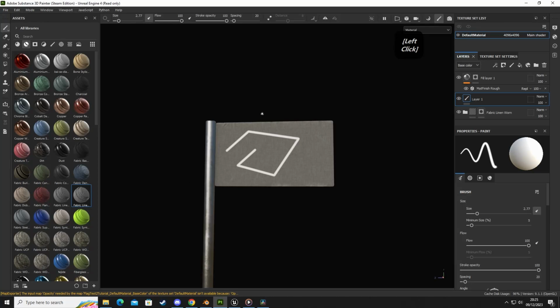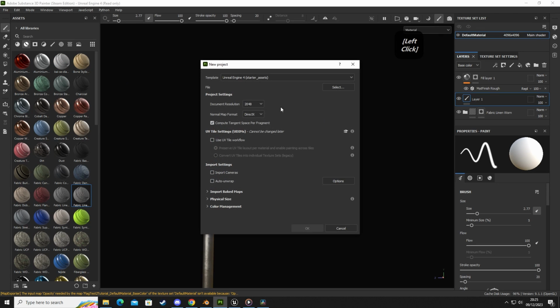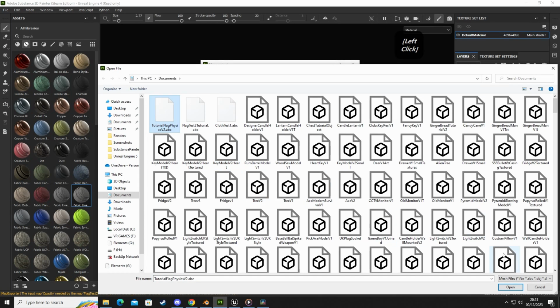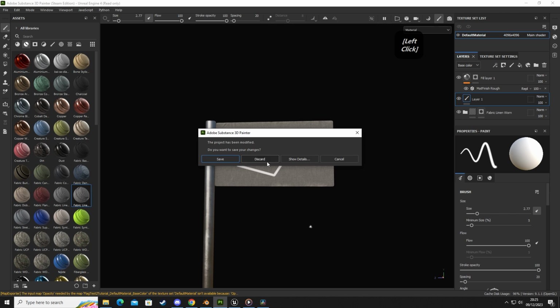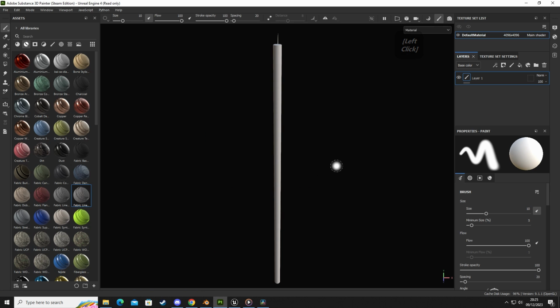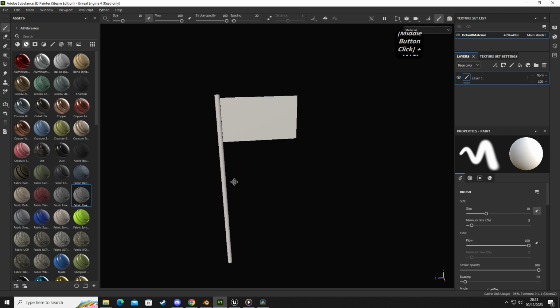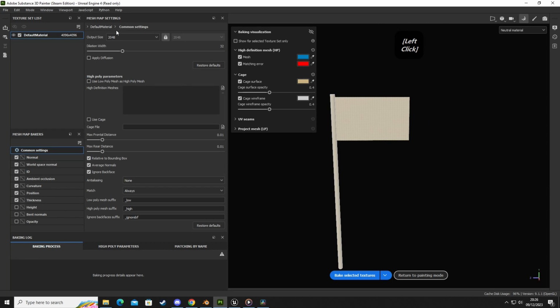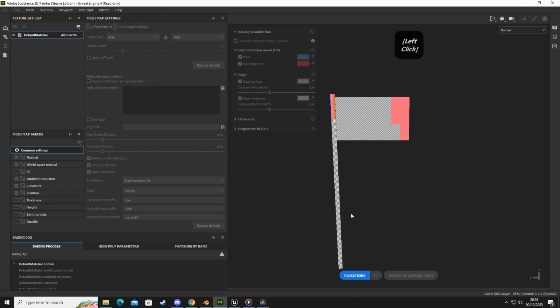And then if you go into Substance Painter or some kind of painting software, it should allow you from here to select your ABC, and that will bring it into Substance, where you can bake some texture maps onto it. So let's get ID thickness. Let's do 4K, none to 16s for anti-aliasing, and then bake. And you can see here that it's got nice clean UVs, and it's baking that perfectly.